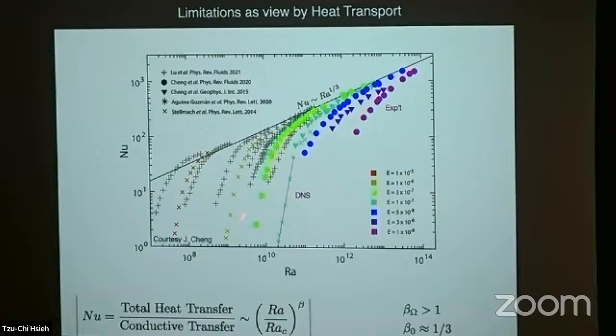So typically what they have done, and in this graph from Jonathan Aurnou, they've reverted to DNS to tell them what's going on in the lower branch here. And of course they're interested in the Nusselt number, and the scaling of it is maybe a proxy for flow transition. It's also a proxy if you're trying to extrapolate out to GFD objects. So knowing the exponents, you can see here, there are some classical ones.